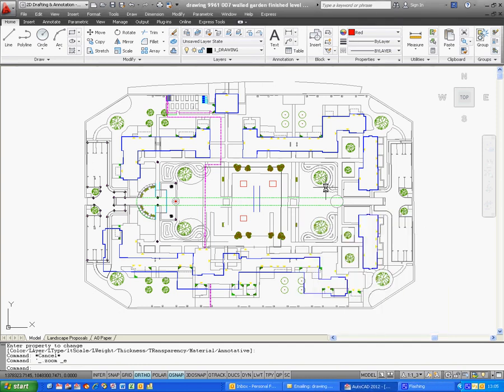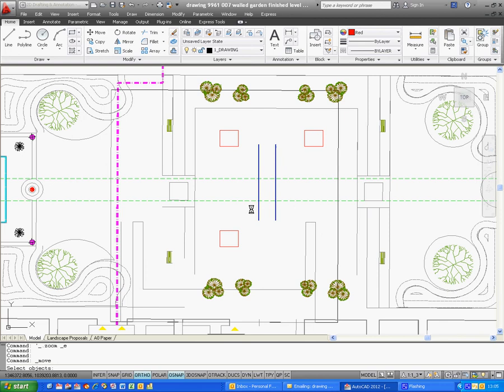This tutorial is all about cross and selection techniques when you're doing a modify command. The modify commands up here on the ribbon, if I just indicate where they are, when you start any of them they all ask for you to select objects. For example, if I start the move command and zoom into this middle area, you'll see on the command line it asks me to select an object.